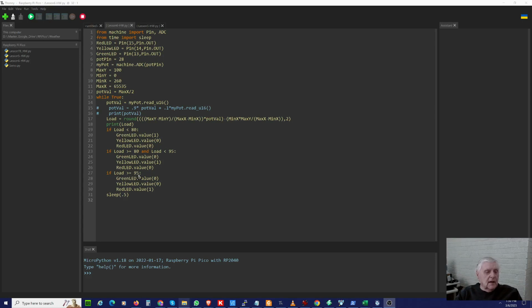And if it's at 95 or greater, it's like an alarm situation. It's under a heavy load. We turn off the green, yellow, and turn on the red. We delay for a half a second and do this over again. So this is in a continuous loop over and over again until something aborts the program.